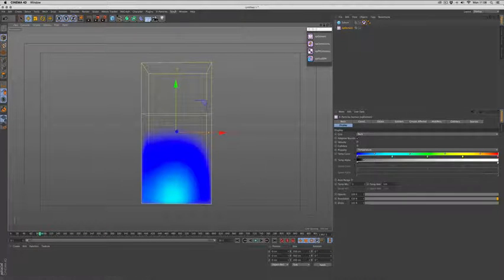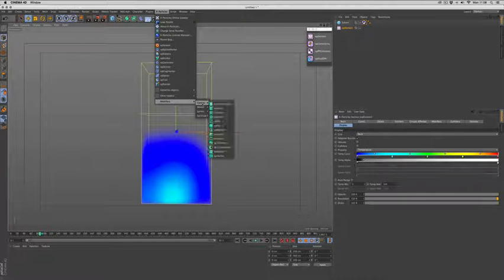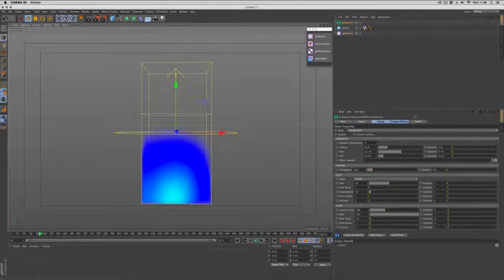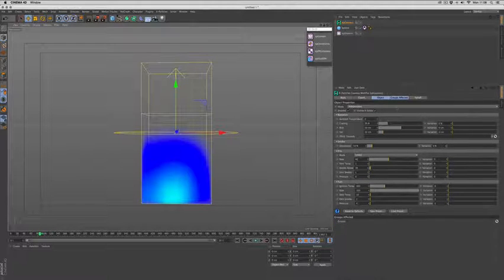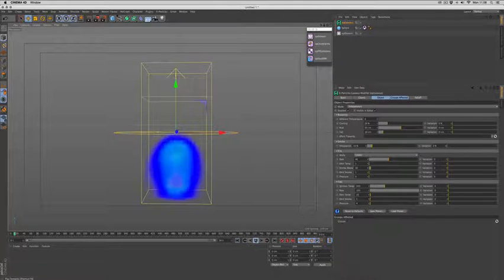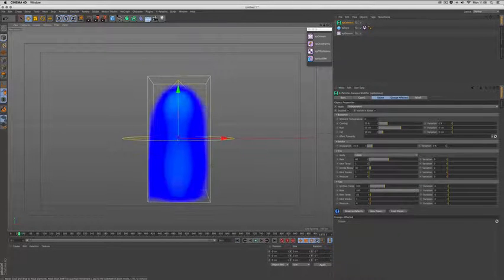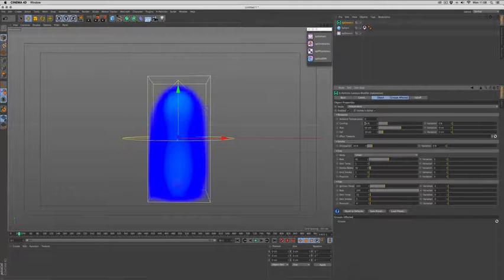So the way to add buoyancy is go to your modifiers, motion, and choose the XP gaseous modifier. This modifier has options to add buoyancy to your scene and also controls over the emission temperatures for smoke, pressure and fire. If we push play now, you'll get a rising smoke simulation. Let's add in some cooling so it's not so fast, 90%, and lower the rise.